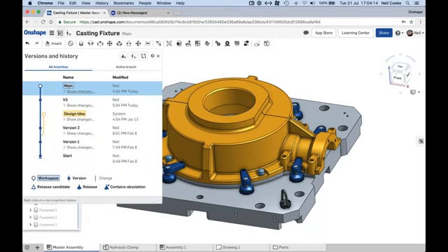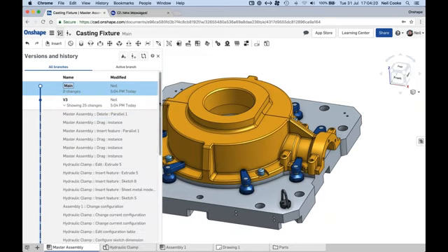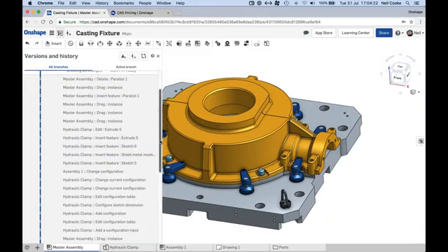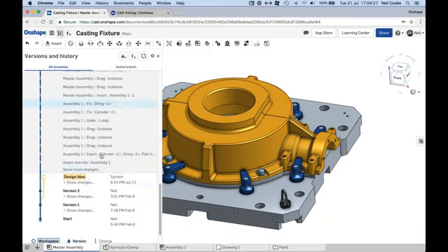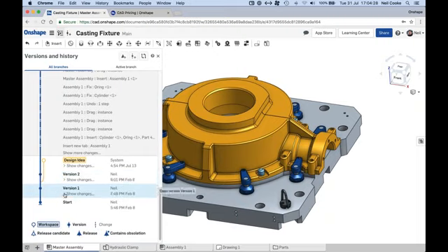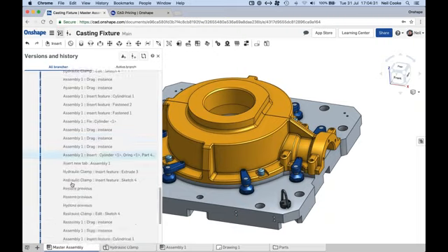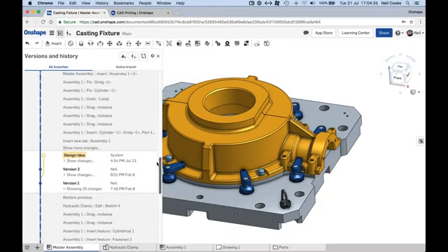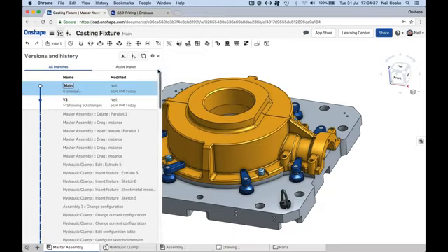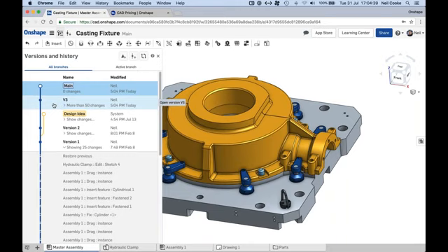And really what a version is in Onshape, if we take a look here, before version 3, which I just created, these are all the operations that I did during this webinar. Okay, so I can jump backwards and forwards. It basically gives me unlimited undo and redo right back to when this thing was first created back in February. A version is essentially just a bookmark or a point in time. If you wanted to do